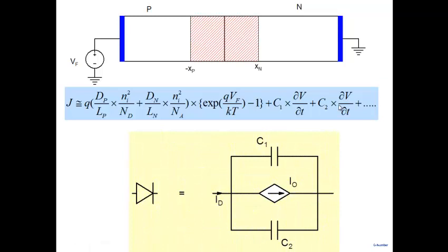So the model that we have is for a PN junction. Now note, under transient conditions, we have the first current, the conduction current, which we represent by a current source because it's voltage dependent. So we have put a voltage dependent current source, I naught, and of course, it depends on the voltage across it only. Okay, so I naught is this current here. In addition to that, under transient condition, we would have a current due to a capacitance C1. We have to find out what it is. So we put a capacitance here, and a capacitance C2, we put it here.